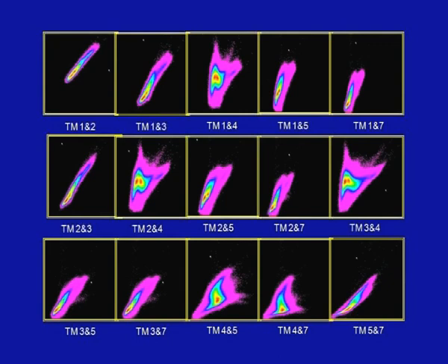So, if we look at the scatter plots between TM1 and 2 or 1 and 3 or between 2 and 3, we find the spread is along an elongated line, but at an inclination from both the axes. This is primarily because of the offsets that may have been produced by the atmospheric effects, which has been reflected in terms of minimum value.